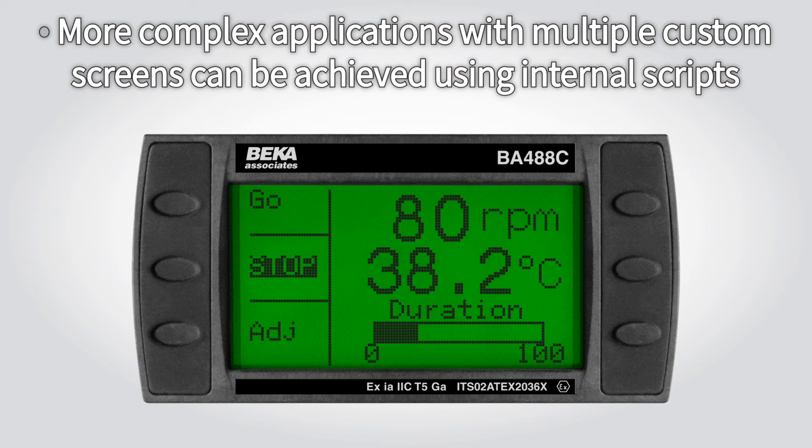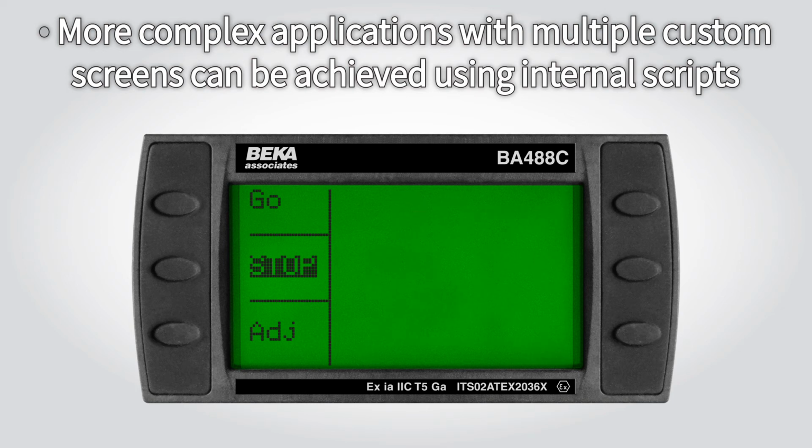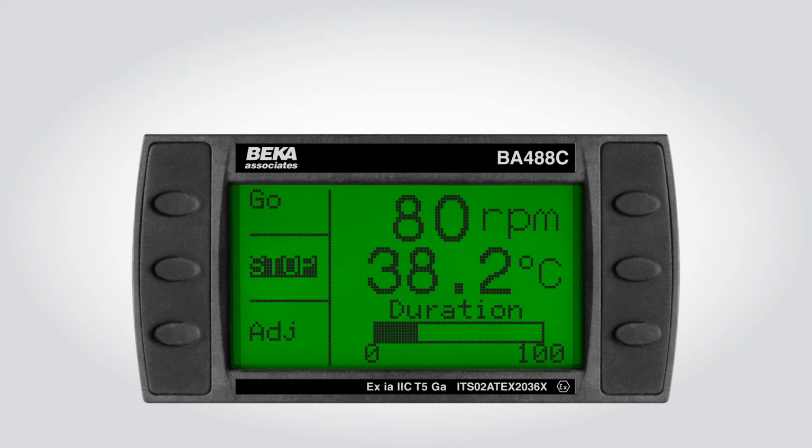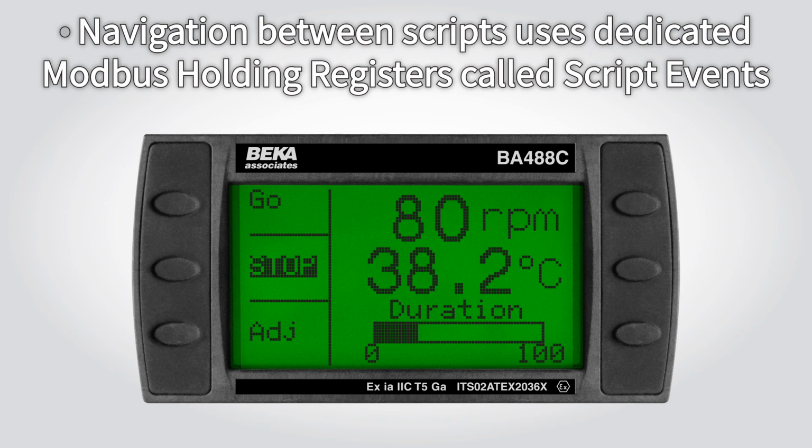In this example, the application requires that speed, temperature and duration are to be shown, and the operator should be able to start, stop and adjust the process. Remember, the BEKA unit is a slave, so all command comes from the master PLC or control system. However, the BEKA Modbus display runs scripts internally to define how data is shown and how to interface with the master, so that when a button is pressed, a script event is initiated.